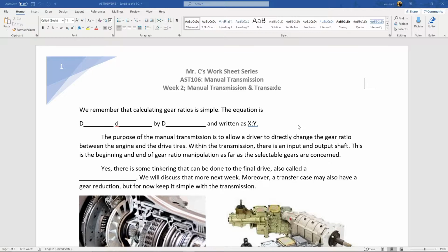If we are talking about a four-wheel drive with the transfer case, there will be some more gears, which will allow us some more gear ratios within it. But in a standard two-wheel drive vehicle, any selection we're going to have for gear ratios is going to be in the transmission. And any automatic or manual, really we're all achieving the same purpose, to allow the drive wheels to go a different speed than the engine, right? So we don't necessarily need a transmission to make the car go.